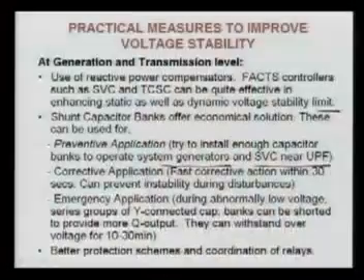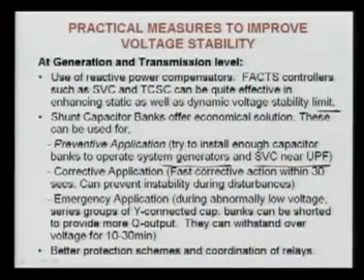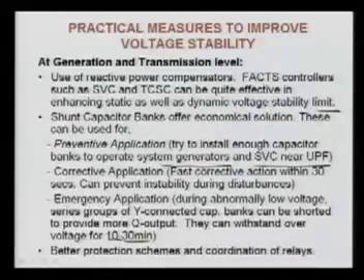So we can use series groups of Y connected capacitor banks, which can be switched in to provide more Q output, and they can withstand overvoltage for 10 to 30 minutes. So we can use some groups of Y connected, that is star connected, capacitor banks. They can provide more reactive power support, and then we can avoid the emergency situation.